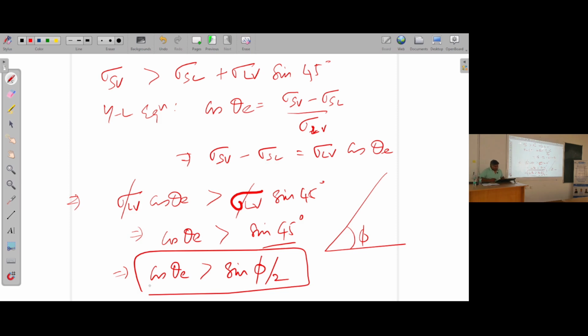And I think this is a very interesting thing. Especially when you design surfaces, say if you want to have a Wenzel structure and you have this patterning in such a way that you've got these poles, obviously it forms a corner and you don't want to fill it. You don't want to have a Wenzel state. So if you can, just by energy analysis, satisfy these conditions, there is a good chance that you will not fill it. So that can be taken into account in terms of the design as well.